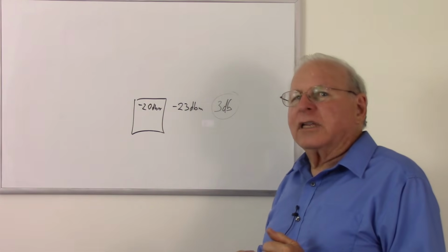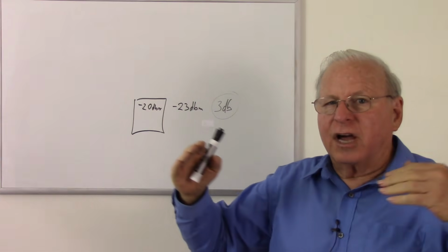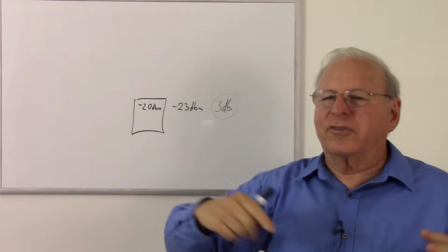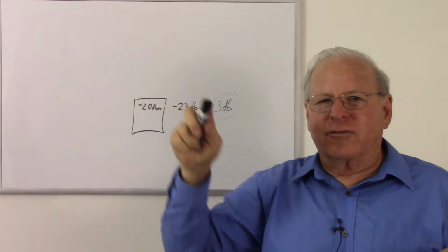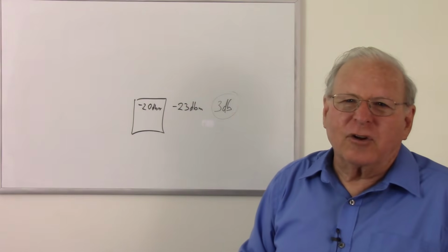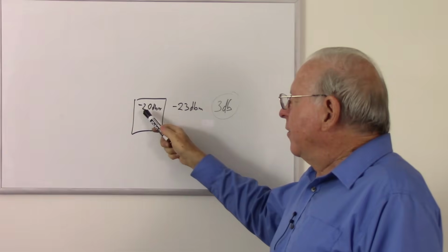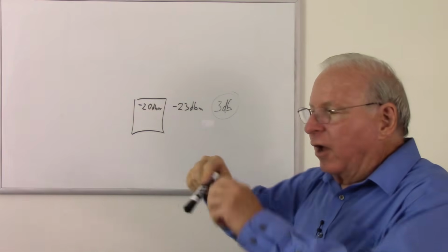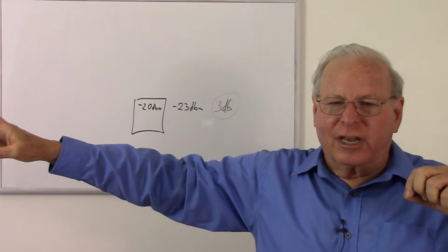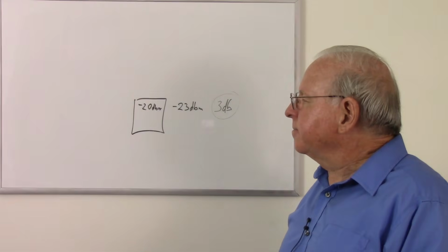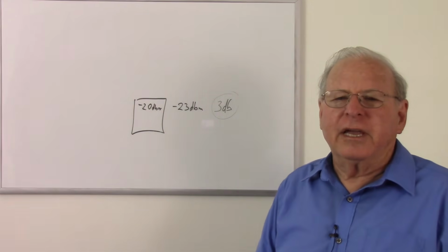A typical link loss budget, which means the amount of loss they can allow in a whole set of splices and connectors and whatever between 2 points, is typically around 20 dB. So we can have down to minus 40 dB on a long cable with lots of splices and connectors and still be within our budget, which is calculated when you make the installation.